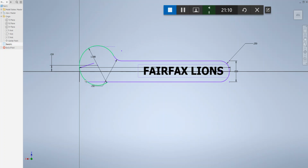So I need to establish a vertical line from this point, and that's supposed to be a 90-degree angle. So I'm going to press the tab key so that the angle is highlighted, and I'm going to type 90, enter. Oh, it didn't work the way I'd like to have it. Control Z will take me back.